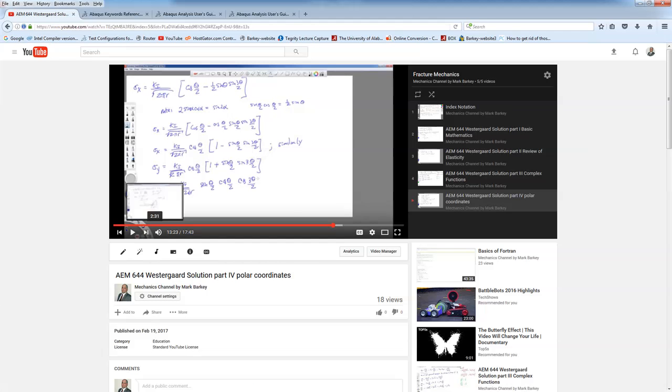When we get these stresses, sigma x, sigma y, and tau xy, now if we wanted a uniaxially loaded plate, what we would do is a linear superposition: we just put a minus far field stress sigma on our sigma x term. And that's an interesting problem to do, but it makes the problem a little bit harder to solve analytically when we do our comparison. So that's why we're going to do the comparisons to the biaxially loaded plate.